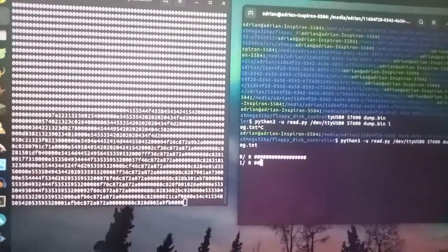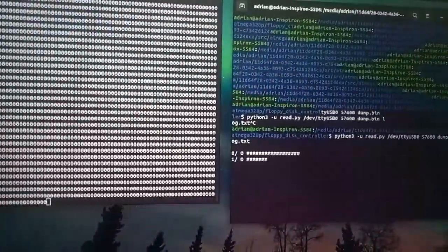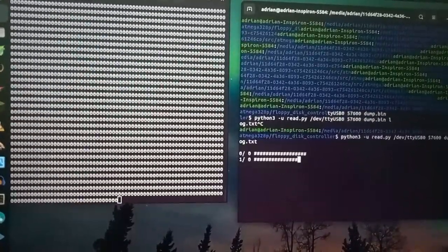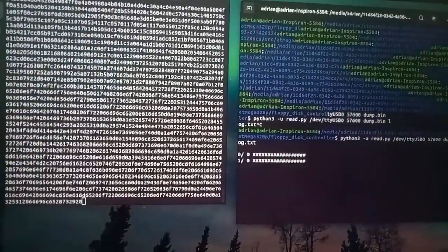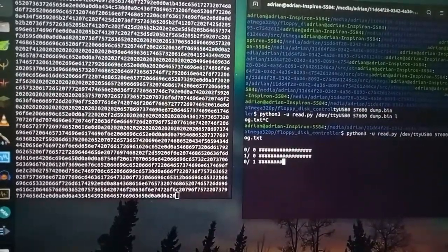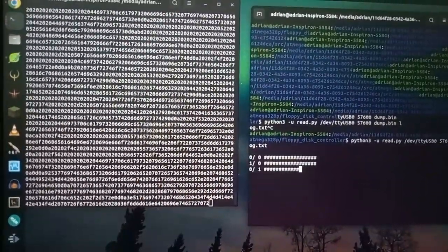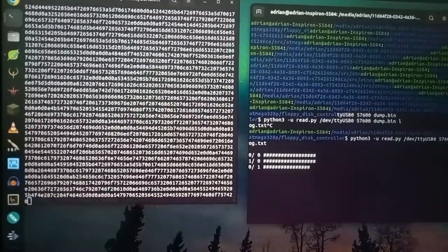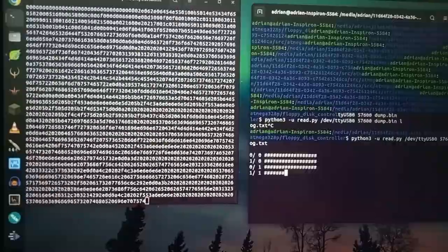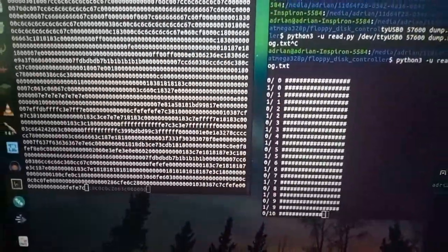When the buffer is full, the microcontroller stops reading pulses and sends the timing to the PC via serial port. The buffer size, created from almost all static RAM of the ATmega328P, is enough to store pulses of the whole sector header and data with sync pulses and signature, plus sync pulses of the next sector. But not to store a full track. To read a full track, sectors need to be read one by one, by introducing some delay after the start of track signal, which slows down the read process a little bit.